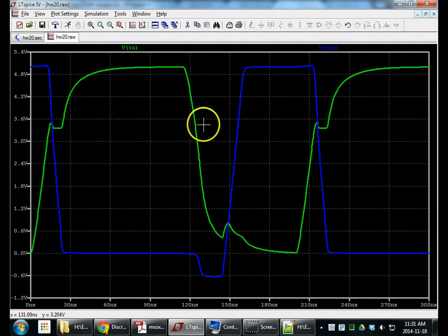And then we go down inside the MOSFET here. There's lots of extra stuff. Remember the BS170, the N-channel MOSFET, had a whole lot of extra circuitry in there. Basically, it's modeling charge storage in the structure, so we can't suck charge out or take charge off of the gate infinitely fast or directly. There's some time constants involved. There's some resistances in series, lots of capacitances. That's what's going on. This goes up, we get this capacitive feed through, this little bump here, and then it goes down, and so on, and it repeats again.